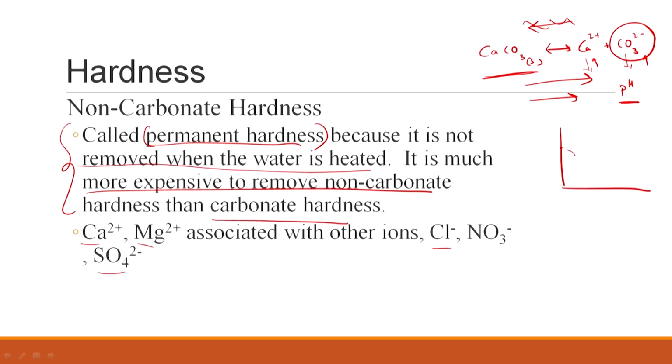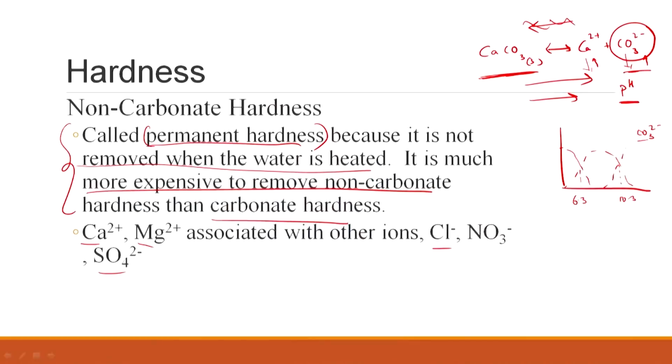As we discussed earlier in detail, in the carbonate system, this is 10.3 for CO3 2 minus, and this is 6.3. So, when you bring down the pH, you can decrease the concentration of the ligand in question, and you can lead to dissolution of CaCO3. That is what you would even see with respect to the accessories in your bathrooms. You have scaling, so you can use mild acids and such to dissolve CaCO3 or the relevant scales that are formed.